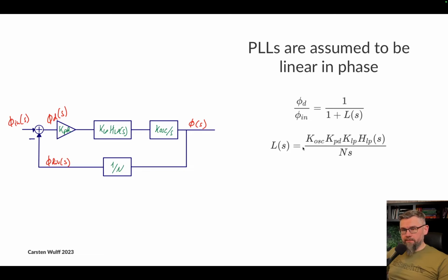So PLLs with a VCO like this is one of the few cases where you actually can have infinite gain, infinite precision, as long as you spend a long enough time. That means that you can make the output frequency of a PLL exact. It is an exact relation with the input.